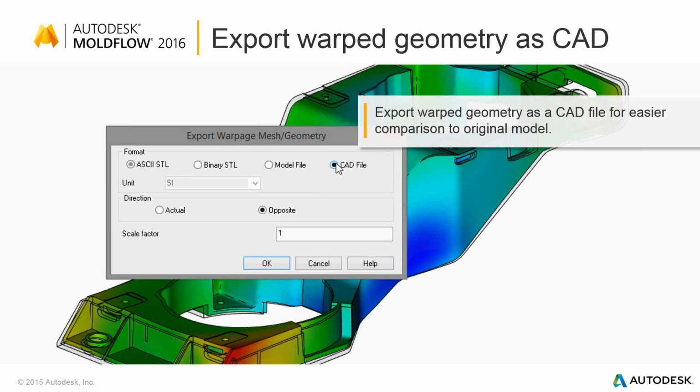Then we typically don't see people using the full warpage, but let's say 70% of that particular warpage, because the actual deformation causes some extra structural stiffening of the part, if you will. So typically people don't apply the full opposite warpage, but a portion of it.